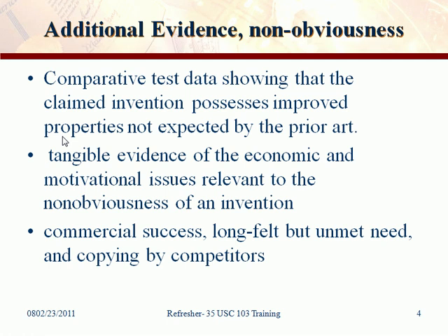If you said to me, well, all of these communicating power outlets are sucking down a lot of power, and that defeats the purpose. They're not very green. They're always using power. But I have an approach that puts the microprocessor to sleep and only wakes it up every 2 hours to do a monitoring. Now, all of a sudden, it looks like maybe you've got a different approach. So if you said, gee, it only uses a few nanowatts every minute or two, and then it adaptively samples, and I've got a new algorithm, maybe that's the contribution.